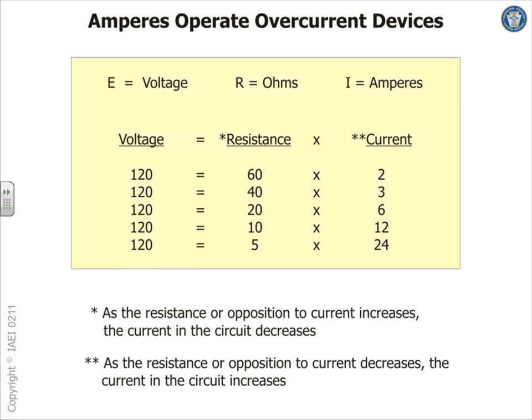You minimize the possibility of people accidentally coming in touch with an energized object. If you ground and bond, the circuit breaker will immediately pick up that an object got accidentally energized, say the fridge frame is energized, bam, trip fast. And number two, guys, if you have a ground fault, the grounding electrode system is supposed to facilitate the flow of current back to the source so fast that the circuit breaker will trip fast enough to eliminate the possibility of arcing and sparking and burning your building.